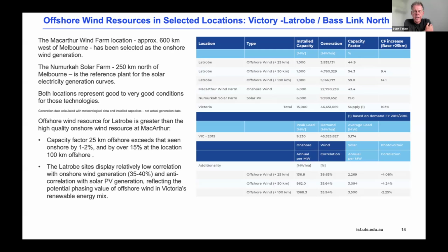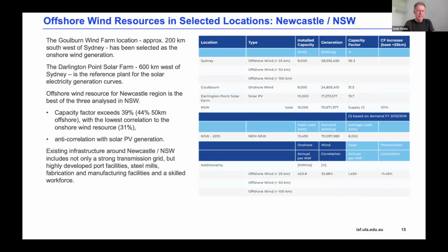And then we looked at the utility-scale solar power plant, and upscaled their generation per kilowatt to 6 gigawatts installed capacity. So let's say we have the location around that existing wind farm and we increase the capacity. What will be the capacity factor? And then, at the last step, we checked when over the year, in hours, the generation will appear. I will skip this because that's the same idea as for Newcastle, and I don't have enough time for that.